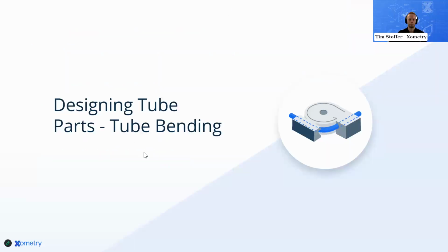Yeah. I know, like the last one was wispy and cantilevered features too. Same. I always say the gravity test. Can it hold its own gravity? Like if you're holding it from that wispy end, is it going to flex on you? That's something you want to avoid, because that means that it can be damaged in shipping. It can be damaged by you. There are so many ways for that project to fail. But laser tube cutting is fairly straightforward. It's very versatile. It's very much a bread and butter exercise when you're cutting this out.